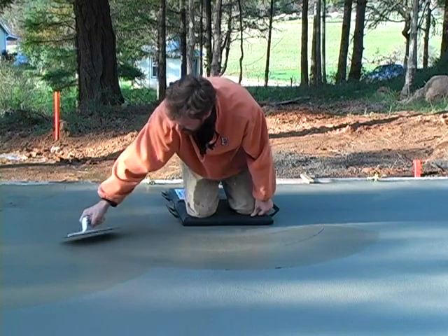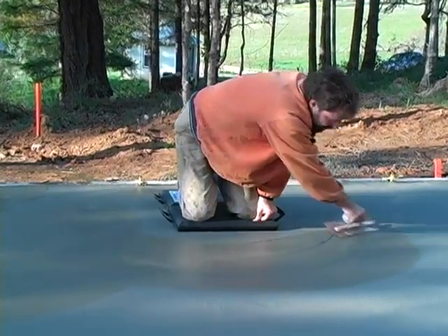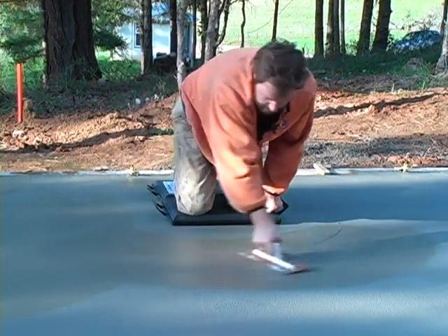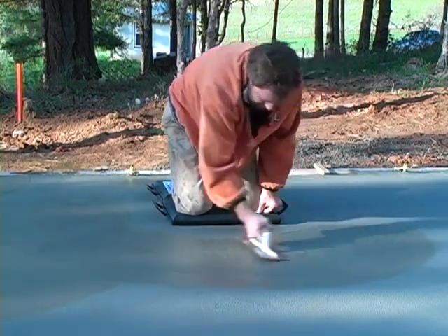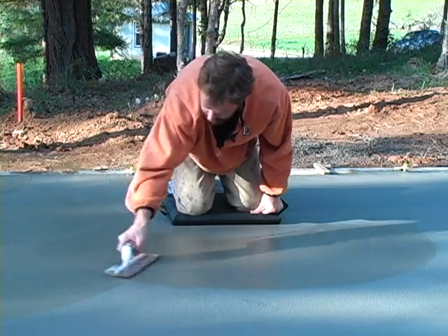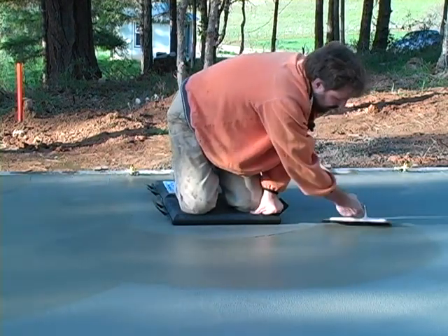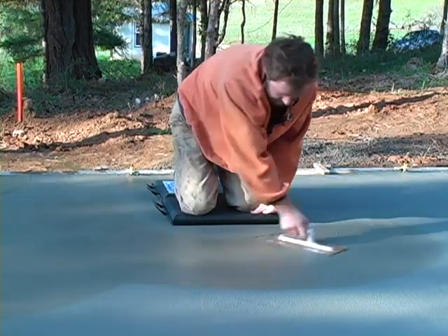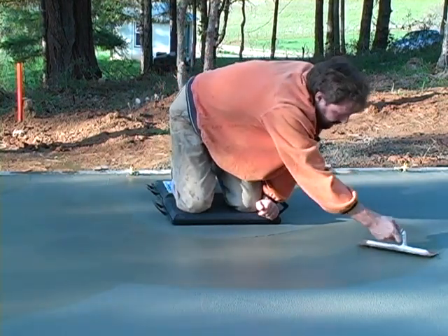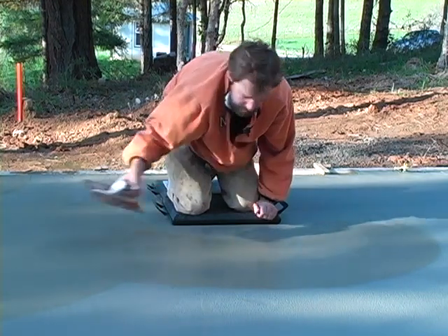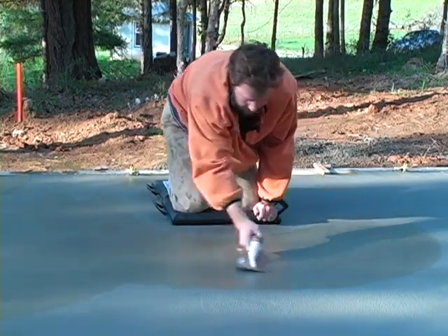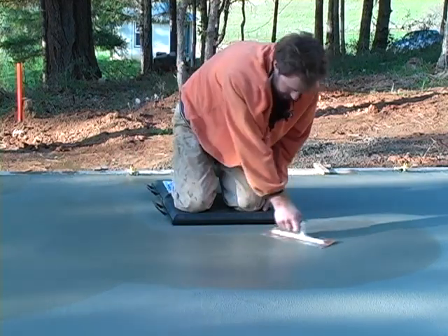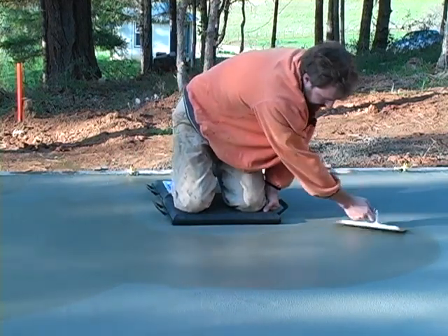You just want to go back and forth and start out with some harder strokes where you're really putting some muscle into it, and that'll help you smooth out any irregularities. And then as you work it in more and more, you can become more and more gentle on the actual trowel itself, and you'll find that the cream will start to work back in to the slab nicely. You want to overlap from where you last were and leave space to overlap in the other direction.